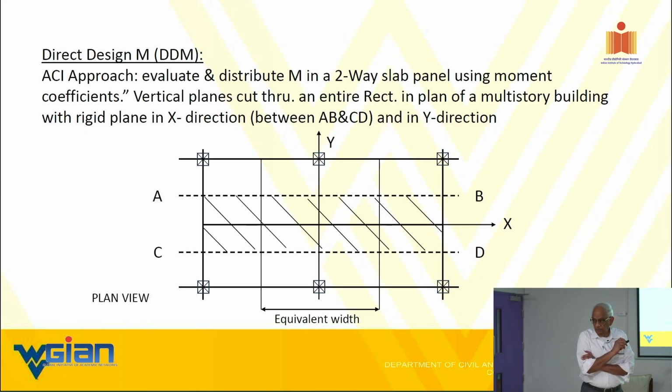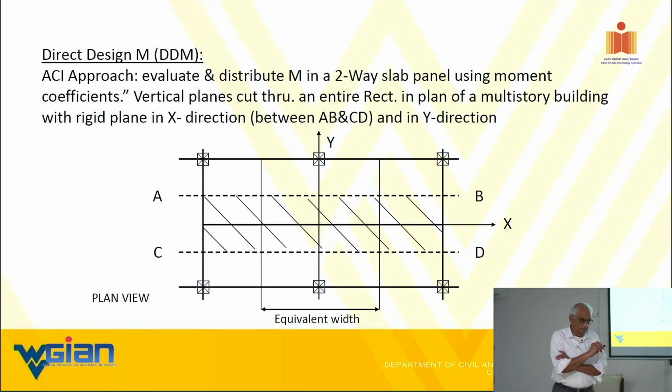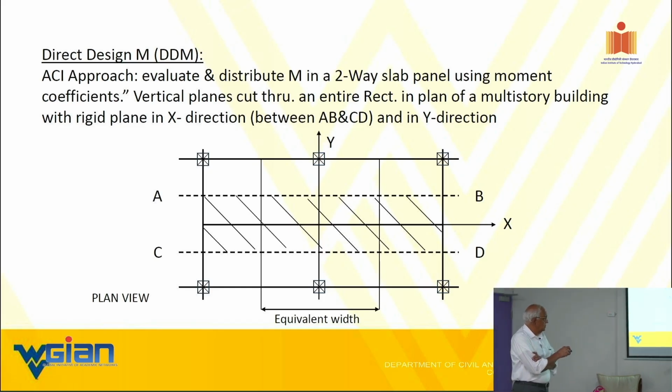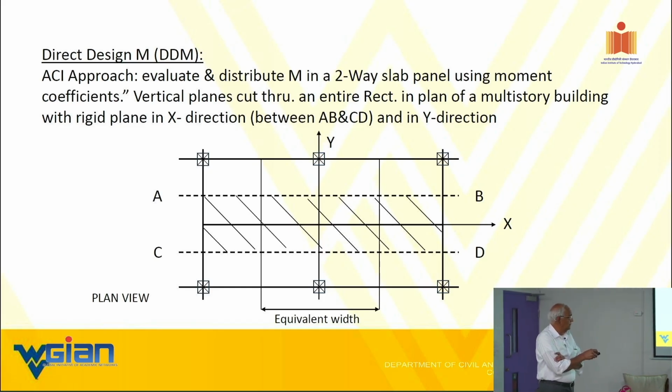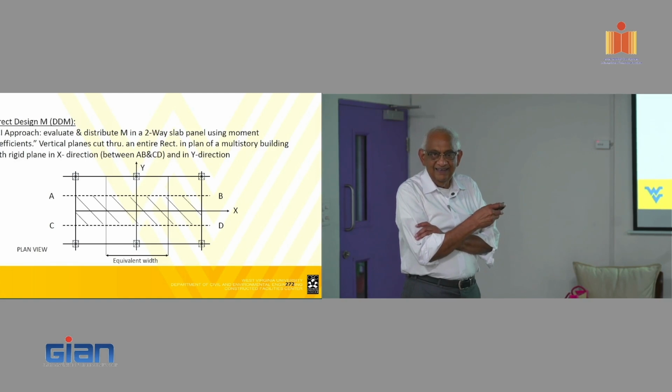You follow? Yes. That is the basis on which the direct design method is, when the yield line theory was developed back in the 1930s. Almost, not quite, 100 years ago. Okay, it still works. There are other theories, better theories, but that, so what is the equivalent width here? Common sense. What is the common sense? Center to center distance.